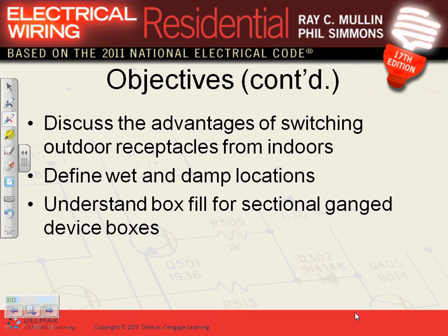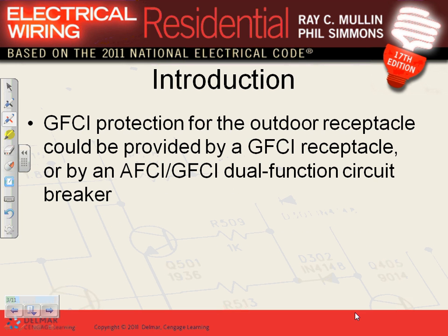You know, at the Square D seminar, he said there were both, but if the GFCI doesn't really work, is it still okay if you put it in and it's listed as such? I've never installed one that has both of them. I believe if you have a GFCI, AFCI rated circuit breaker, it must work. You can't just put it in if it's not working. Most of the people, guys, what they do is put an AFCI circuit breaker right now and a GFCI receptacle.